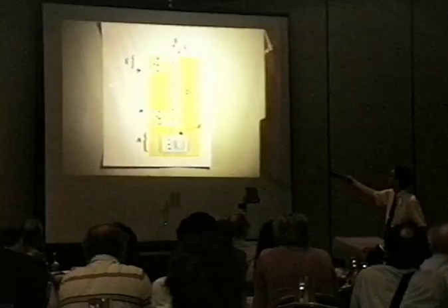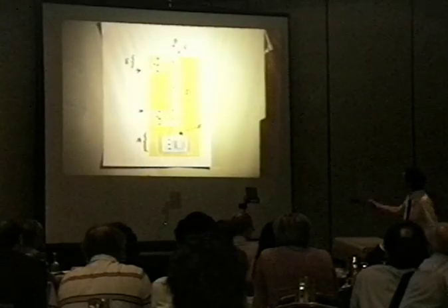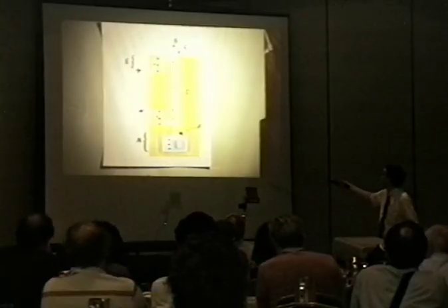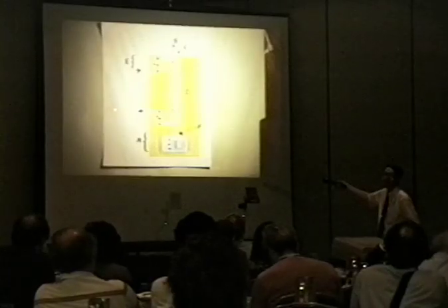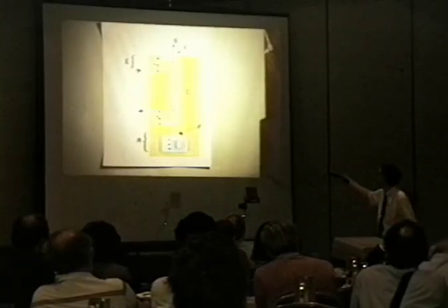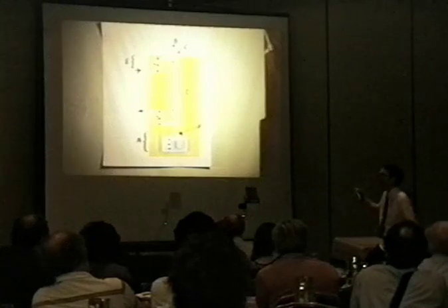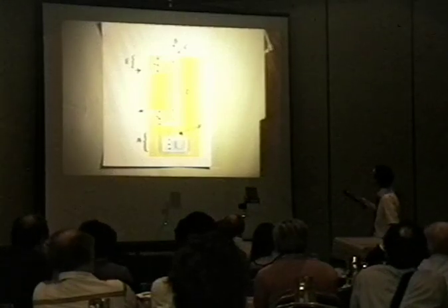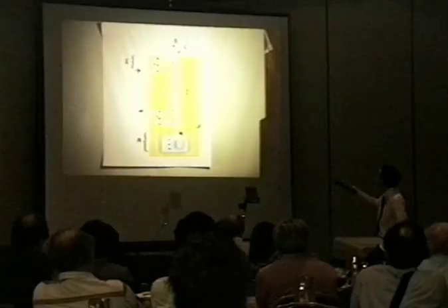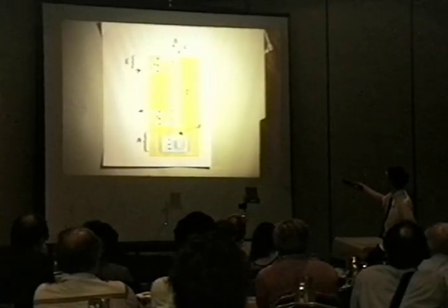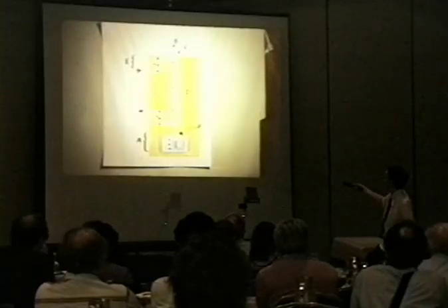I set my water bath at roughly 40 degrees. I try to keep my delta T at 20 so that the output is around 60 degrees. So I change my flow rate to keep a constant delta T. That's just mechanically done. I can monitor the delta T and that sort of stuff too, but I usually set it in there. And what this does is the bottom portion of this is around 60 degrees.